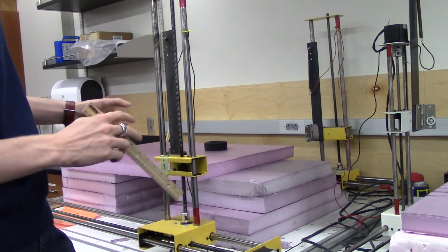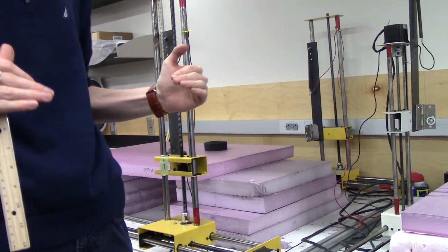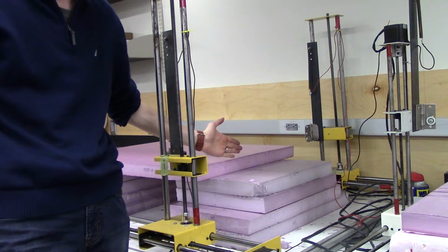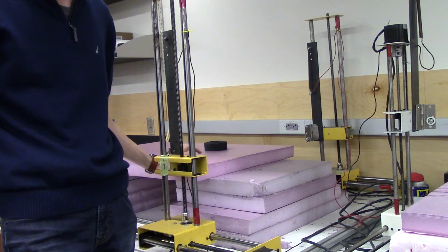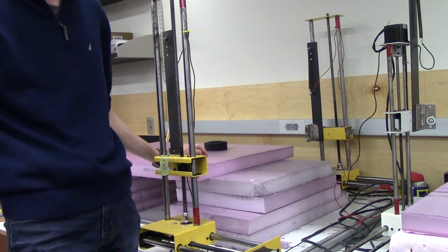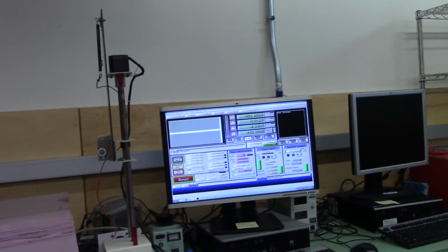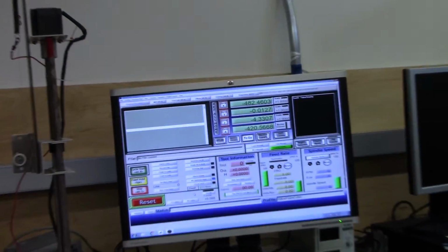And so now I know that my wire is centered in the X direction on both carriages and the Y direction on both carriages. It's nice and flush with the bottom front of the sacrificial foam that I have here. If I were to move it down farther, there is some space between this top layer of the sacrificial foam that the wire will not cut down into. So, moving back over here to our Mach 3 program. Zoom in here.